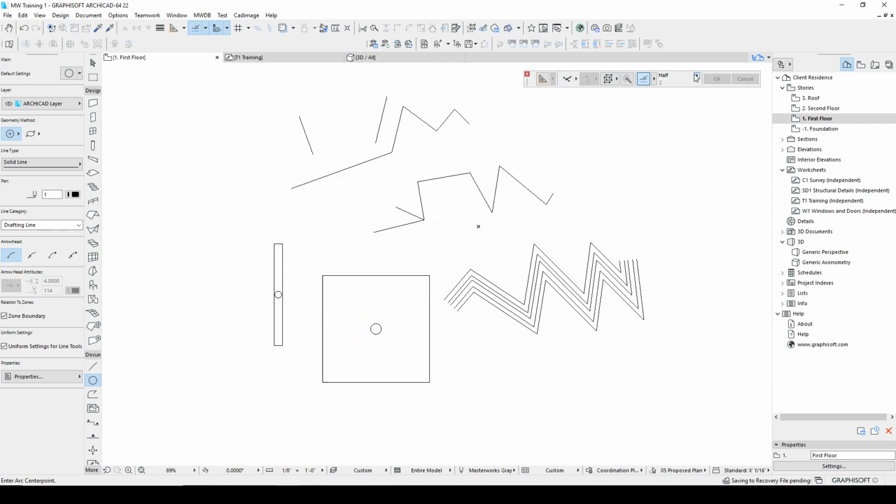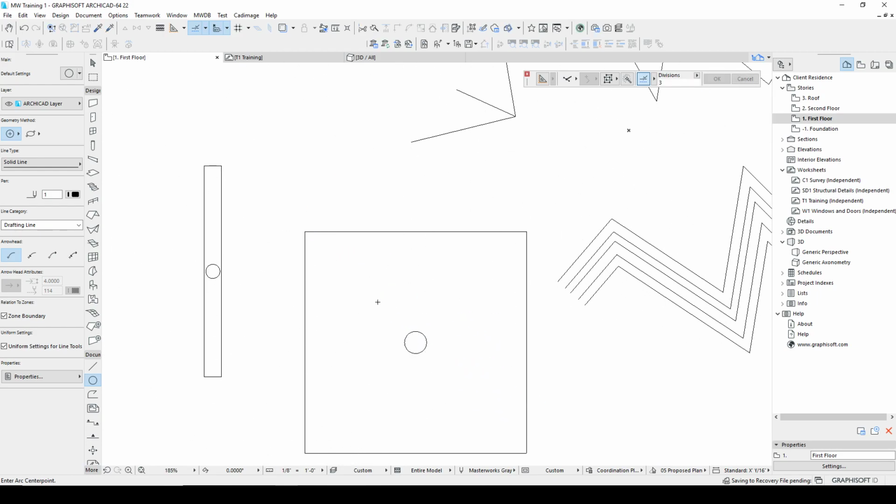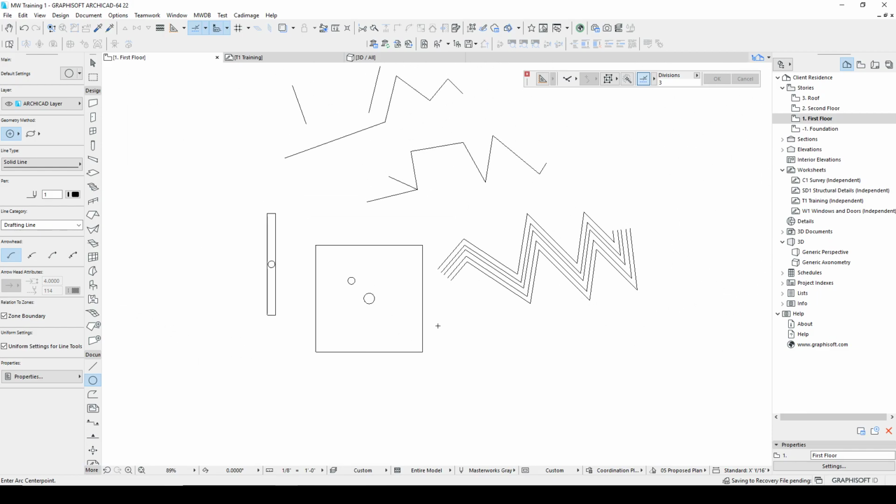And it also works even if I'm doing divisions. I do the same thing. Let's say I want to draw a circle. I select my line, hit semicolon to turn it on, draw the line, and now very faint, but there's a point right in there, and you'll see them light up. And now that's the 1/3 point. So give that a whirl. I think you'll find that to be very useful.